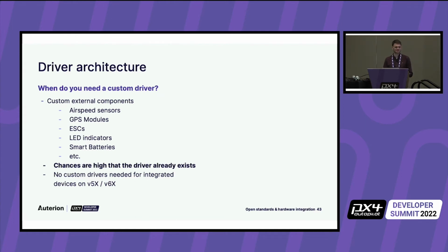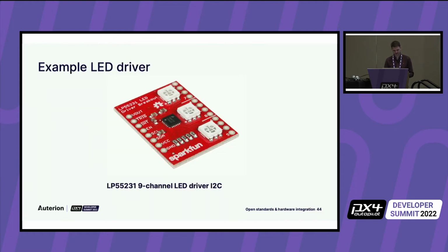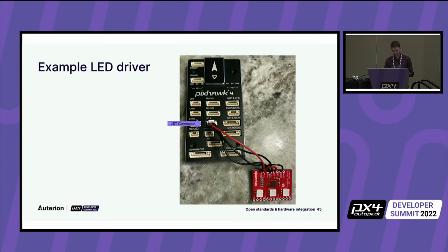So I had a pretty hard time finding any component that I could do an example for this workshop that didn't already have a driver in PX4. It would have been a bit useless to write a driver that's already there. So I found one, which is an LED driver, I think a Texas Instruments RGB LED driver. It's an I2C device. And I just soldered on, I made it standard compatible, right?